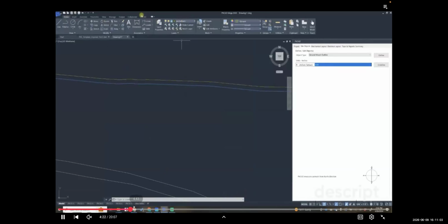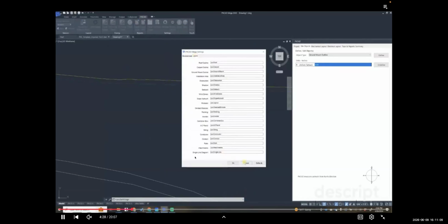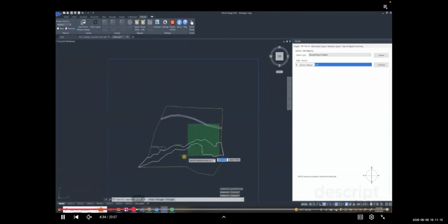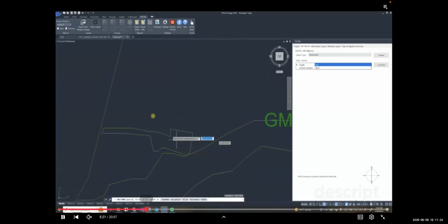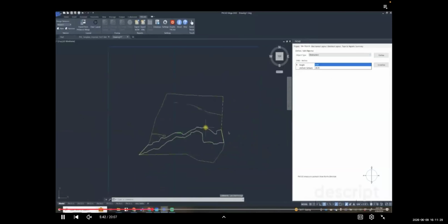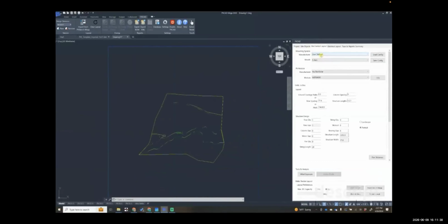Right. So then we switch to the mechanical layout, and these are all the layers that you can also define in the system, right? So all the obstacle setbacks are defined as different layers here. When you switch to the mechanical layout, which is the third tab, on the right, you can basically now add different types of trackers, right? So I'll just wait for this to complete, and then in the mechanical, you can use either fixed or single axis trackers. So we're already integrated with that.